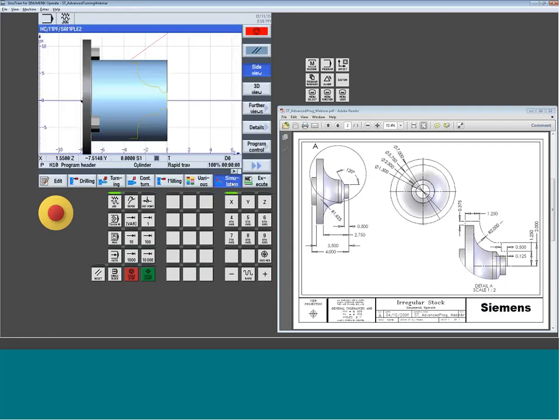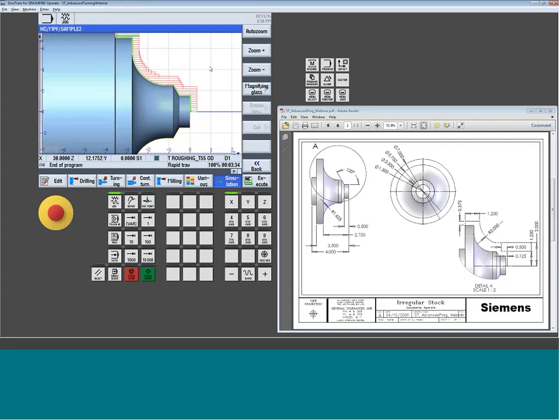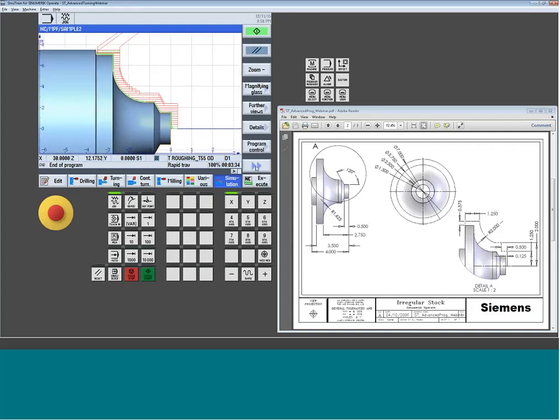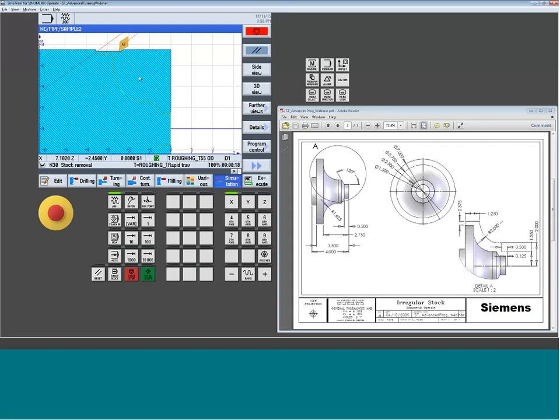Now, the stock that you set up in the header page only supports a blank. So you're going to understand, obviously, in your application, that's not there. So we're going to kind of negate the fact that it thinks it's machining through a bar per se. A lot of times what I like to do in this example, I'm going to zoom in here for you so you can see it a little better. I may not look at the entire side view. A lot of times I'll put it to the half cut view, so then as I simulate, I don't lose the insert. I get to at least visually see the insert the whole time so I can better understand what the actual cutting strategy is going to look like as it drops down through.